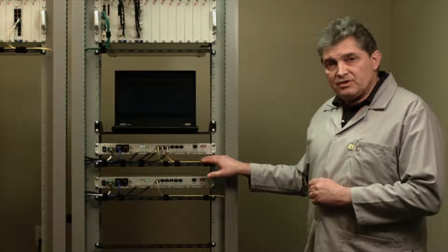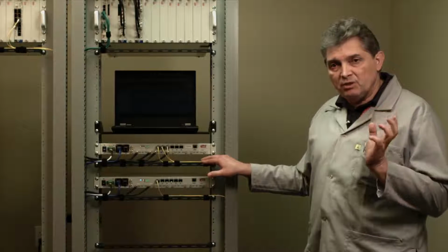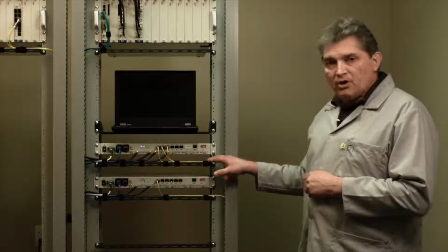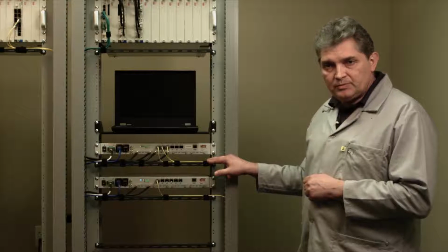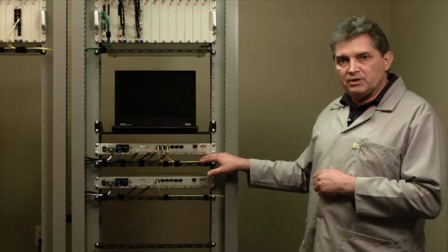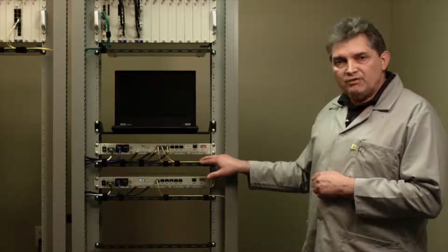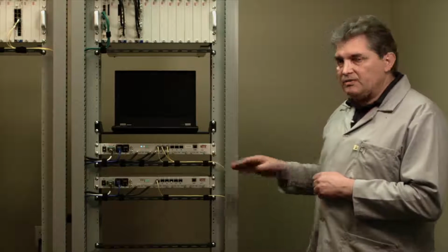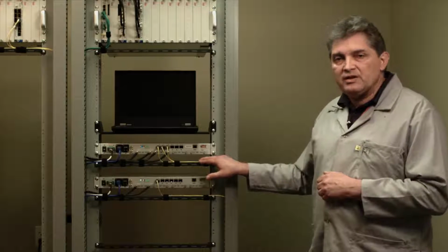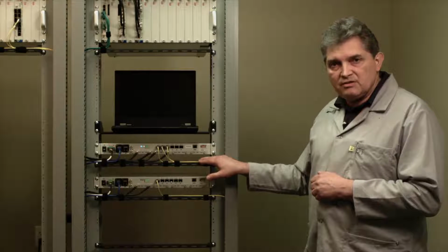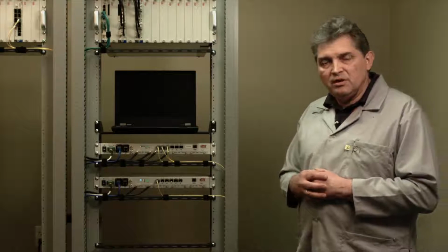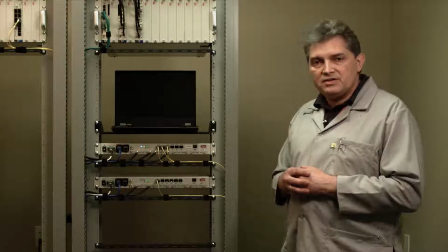The interface between the host unit and remote units is achieved by means of fiber optic cable. The transport protocol on the fiber optic cable is modified CPRI. The data rate that the T-Series distribution system supports is CPRI rate 6, meaning that the speed on a fiber per wavelength is 6 gigabits per second.